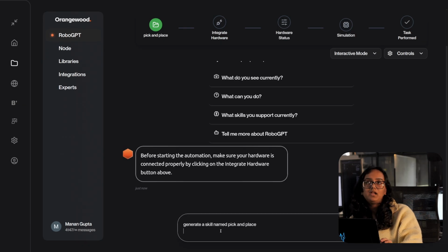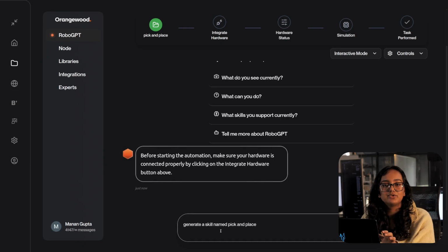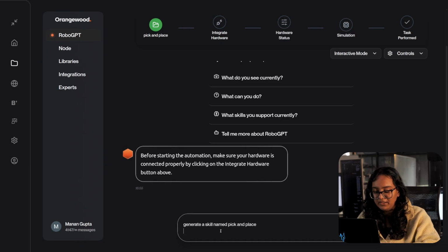And then if we want to perform a pick and place operation, right, what do we need? We need a picking pose. We need a pose so that the robot can go and retract to then move to the place pose, right? So a pre-pick pose, a picking pose, a pre-placing pose. Now these pre-picking and pre-placing poses are just for safety purposes.